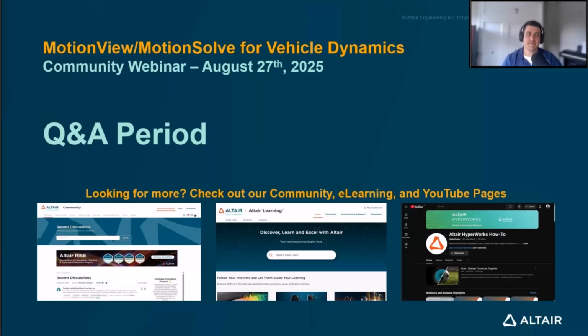Yeah, so elaborate a little bit on that. Fiala as well as MF tire, which comes from Siemens. Both of these have reduced data requirements. So with as few as five to 10 parameters which describe the characteristics of the tire, you can start a full vehicle model. There's no need to wait for an empirical data set that's required for all the advanced tire models. So that's something you can get started with really easily.